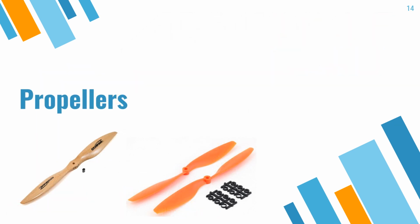At last, the propellers. Where would we be without those? Propellers come in different materials. Think about wood, plastic, carbon fiber, and in the case of the orange ones shown below, nylon. These nylon propellers are also used for the DroneBox, and they come in different colors. When you go to the testing data of your motor, you will find a prop specified there. So in the case of the BR2212, you'll see we need a prop with the code 1047.